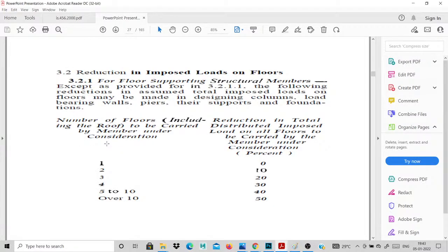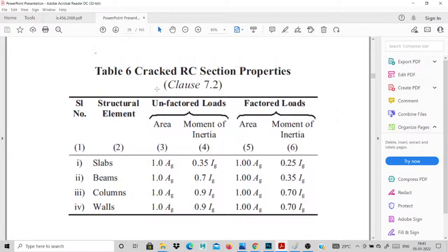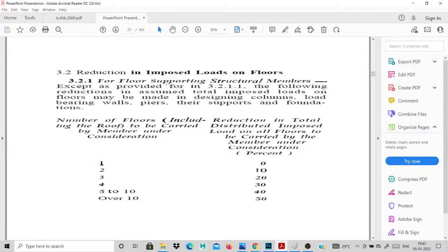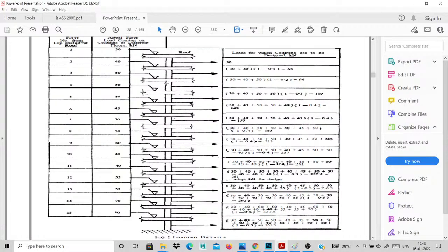This is the main one. You reduce the column member only, not the beam and slab. It reduces the column member only. It's a compression member, so automatically you reduce the column member. The footing and others come under smalls. Okay, this is the main advantage to reduce your column size and AST values for your areas. This is the main one, imposed load for your columns.